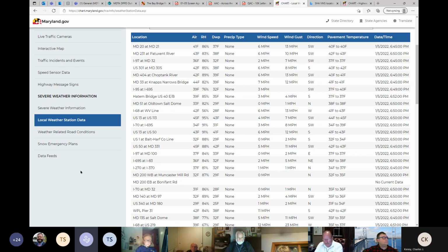There are times that we know what the wind forecast is going to be, especially, think about how a hurricane works. You know, 4, 5, 6 days ahead that you're going to get a hurricane, and these are going to be the wind factors. We also get wind data hours ahead saying we expect the wind to pick up, maybe 50-mile-an-hour gusts by 2 o'clock in the afternoon. So we can't wait until 2 o'clock when it actually happens, because if we're in contraflow, we have to come out of contraflow. As you know, that takes about 20 minutes to a half hour. So we would have to be deactivating contraflow earlier than what somebody might be looking at that wind factor. You see what I'm saying?